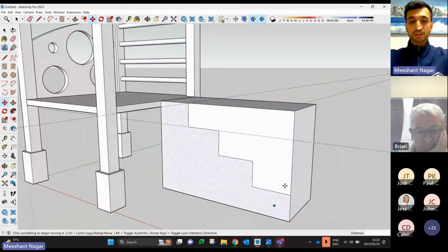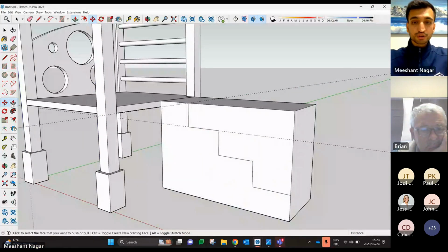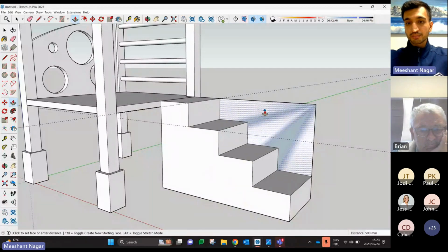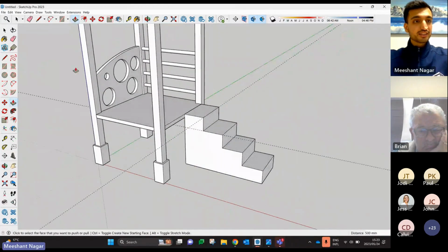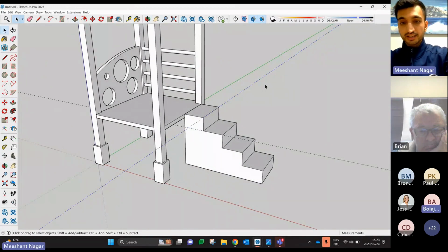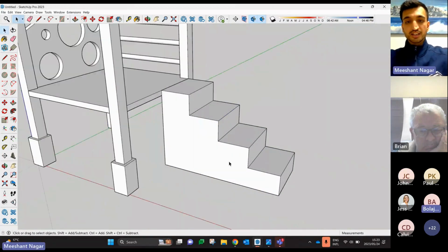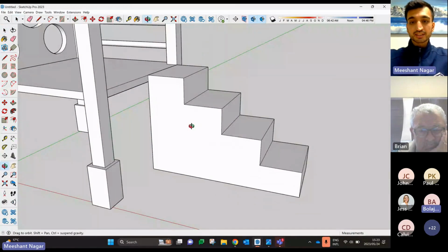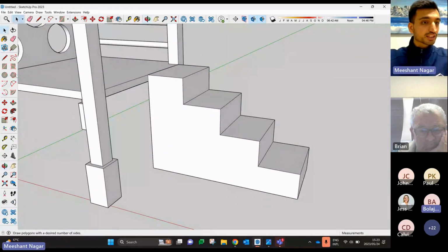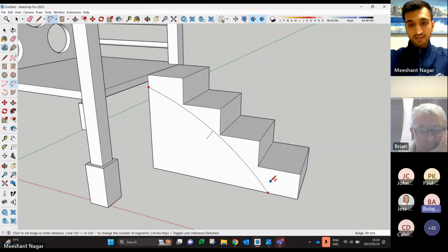As you can see, it's already put in my geometry for me. And now using push pull, removing the top. And there we go. There we have a stair. So remove my dimension lines. And I'm going to, as well, we can maybe make the stair a bit more fancy using 2-point arc. Using 2-point arc, going from there, let's go from there to there. Maybe make a slight curve.